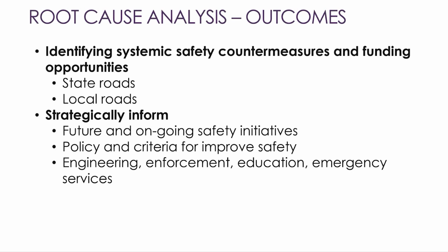But the main thing that came out of the intersection analysis is that there really is no one root cause. You have so many different types of intersections. You have a 6-lane intersecting with a 4-lane. You have a 6-lane intersecting with a 2-lane, unsignalized two-way stop control. Once we get into the alternative intersections and their acronyms, it's really challenging to find a single root cause. Even thinking through just a signalized intersection, you have potentially different phasing alternatives as well.